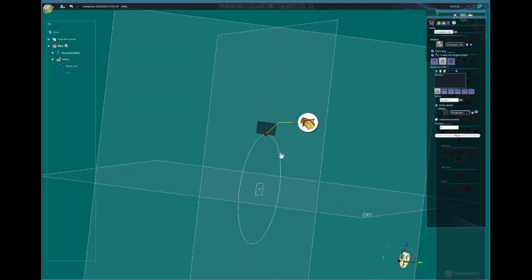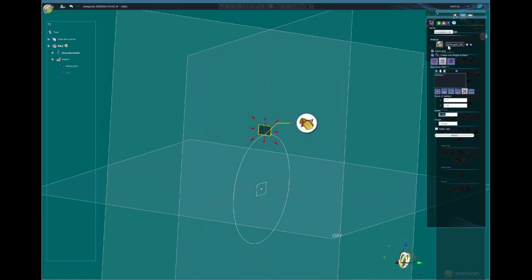So now we can decide how big we want the band to be, how thick, how wide. So I decided already that my band is gonna be 2 millimeters by 1.5. So let's uncheck keep ratio. We're gonna do 2 millimeters by 1.5. You see that changed already. And you're gonna go with white gold 14K.